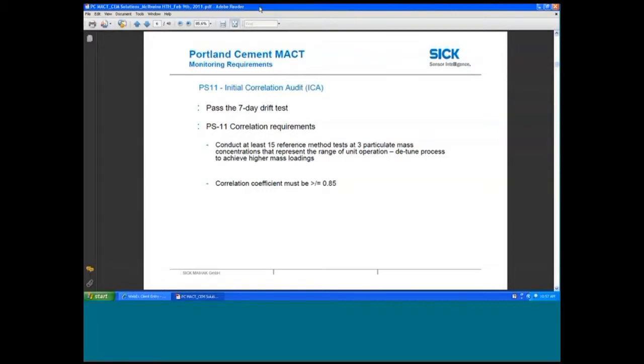Carl alluded to the test that's going on up at DT&E, where they're testing a number of PM-SEMS and also testing this QA/QC device that generates aerosol of particular concentrations as a surrogate to test. There's also tests going on where people are collecting fly ash from the baghouse or the ESP and actually re-injecting plant fly ash into the process using mass balance and things like that to generate these.